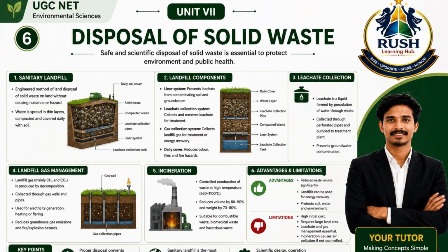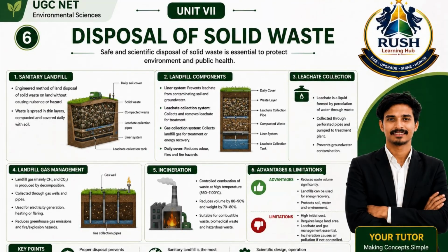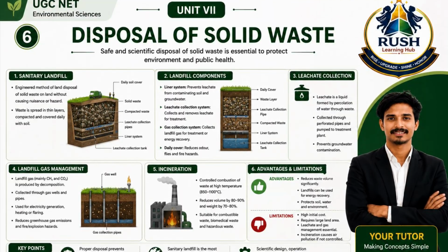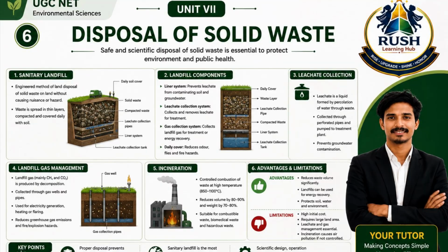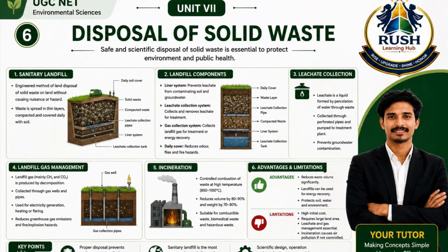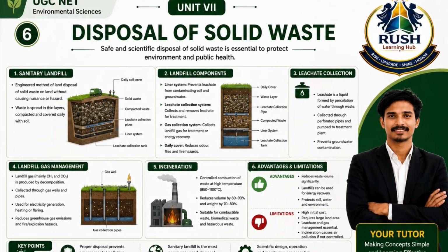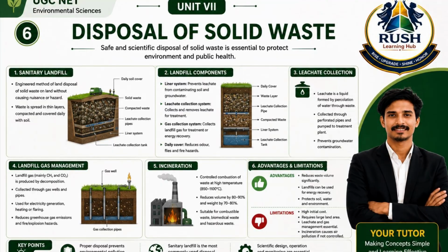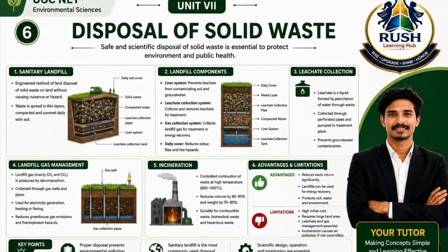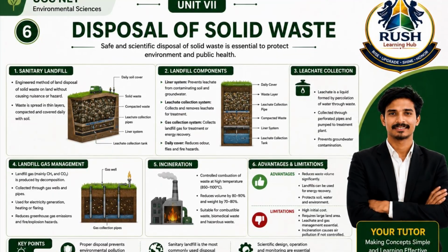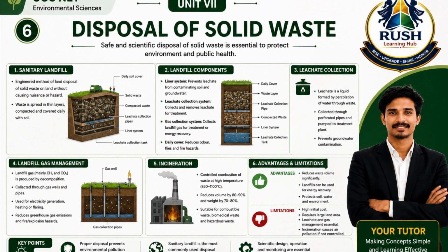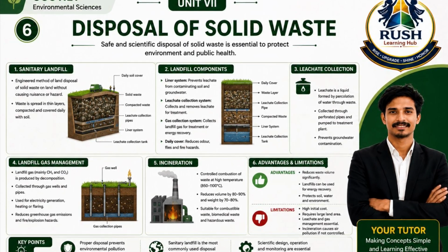Effective landfill management includes regular groundwater monitoring, leachate treatment, landfill gas monitoring, storm water drainage, slope stability, vegetation management, and post-closure monitoring. These activities ensure that the landfill remains environmentally safe throughout its operational life and even after closure.